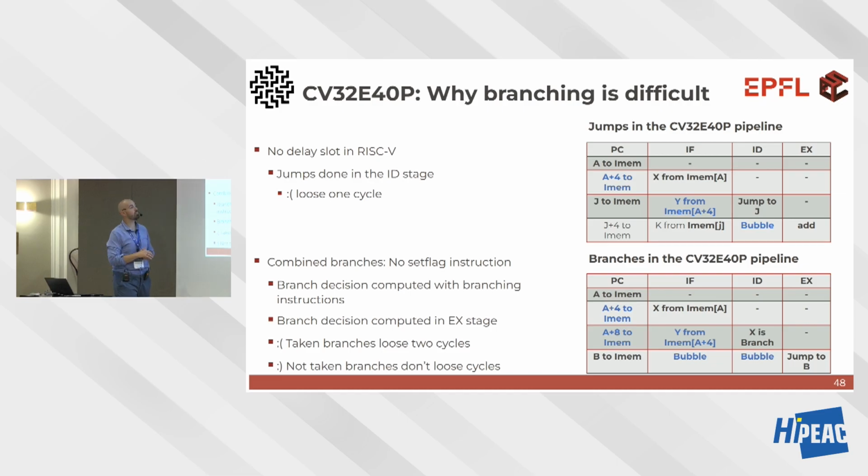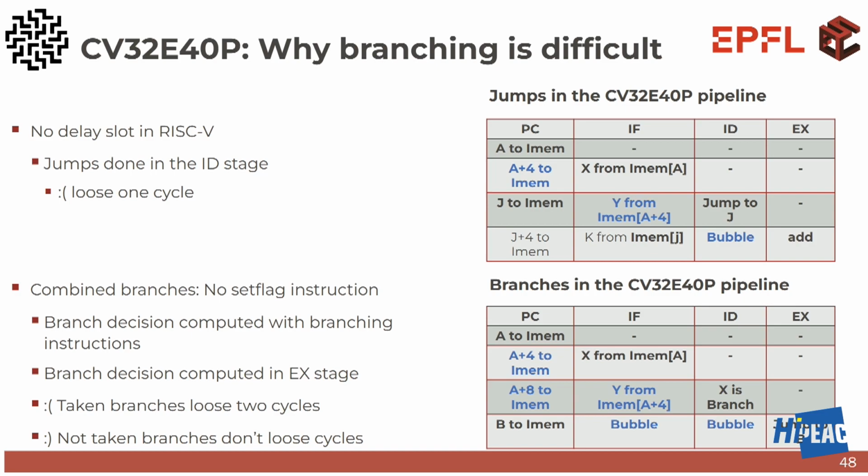Now, similar graph than before, pipeline stages. I'll let you guys play with that, but very similar, but different performance now. So here jumps are done in the third cycle, in the third pipeline stage. So I'm wasting 2 cycles again, but for a different reason. But I let you guys play with this.